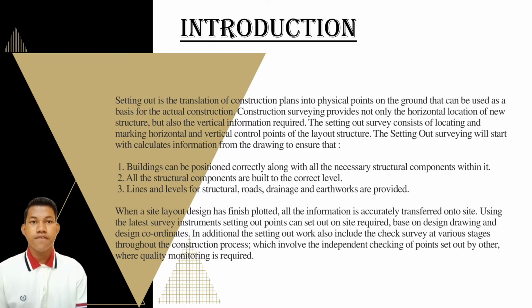Using the latest survey instruments, setting out points can be set up on site as required, based on design drawings and design coordinates. In addition, the setting out work also includes check surveys at various stages throughout the construction process, which involve the independent checking of points set out by others where quality monitoring is required. So that's all for me. Next, I will pass to the next presenter.